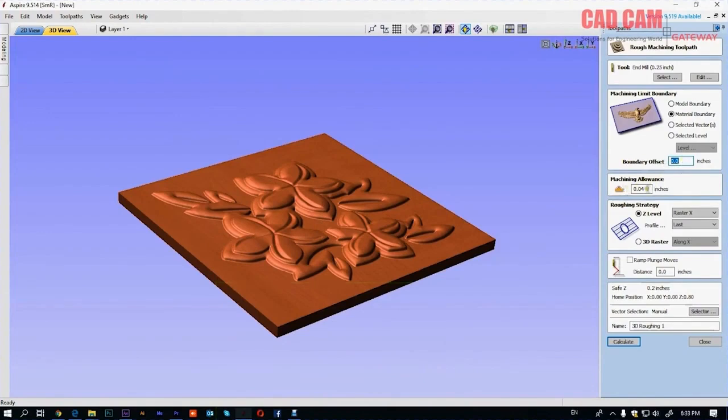Here I did this. Here, seeing the machining, I left the allowance. We will give that allowance of 0.04 for the next finish cutting. Now that we are doing the roughing machining, you leave it like this for now.